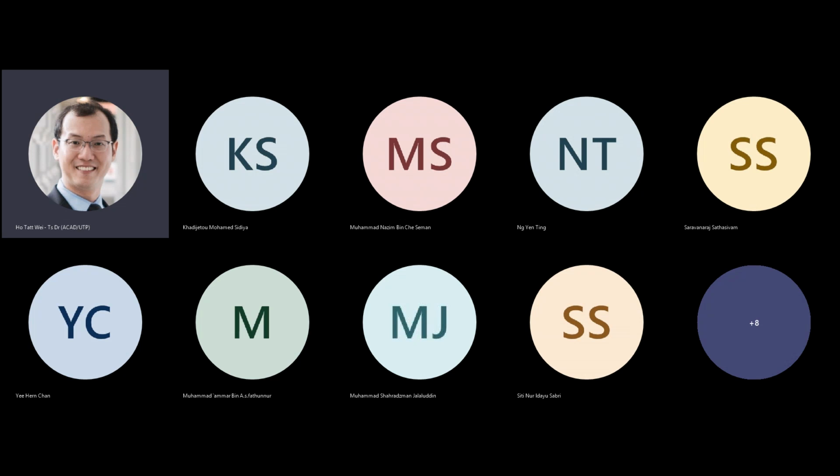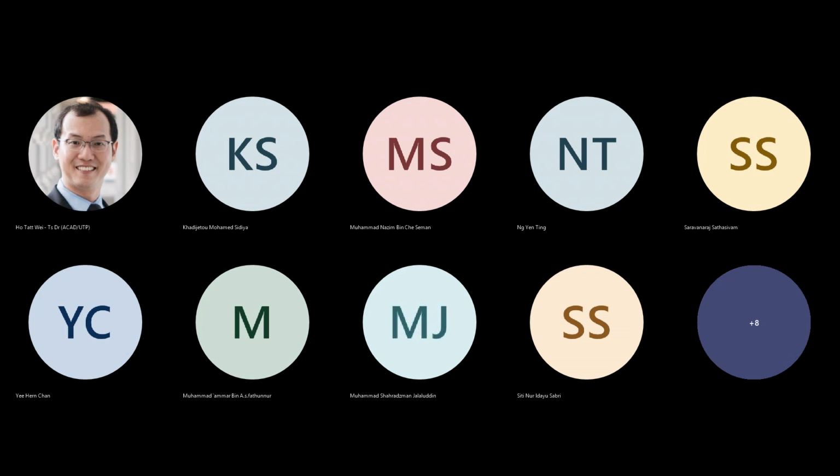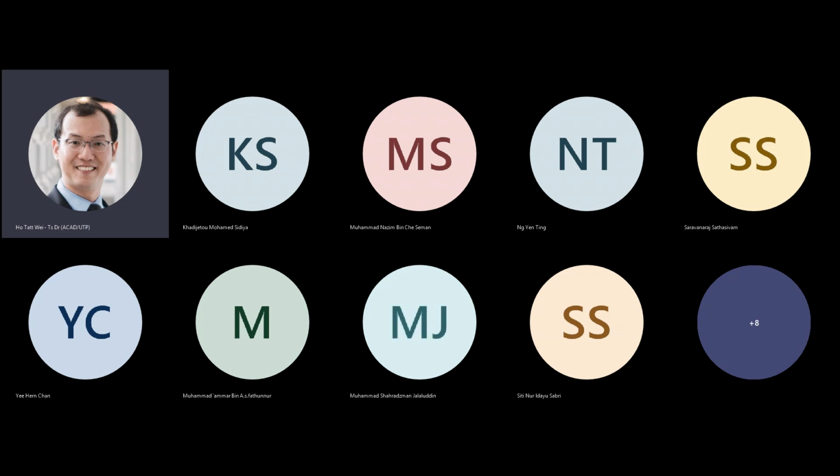So back to this transistor, this is the gate, this is the drain, this is the source. Now, remember, we always talked about putting an oxide layer here, and then you have a metal conductor here. This oxide layer is an insulator, and guess what? You have a conductive layer, insulating layer, conductive layer. This forms a capacitance.